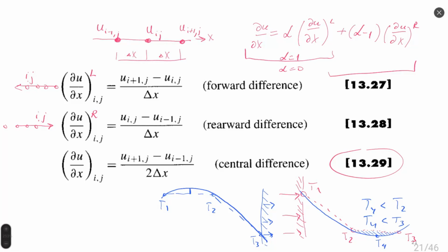Approximation by a line is called first order approximation, and you can find it in solution methods when you use ANSYS Fluent, you already remember, right? That you can choose first order approximation, second order, third order, etc. So first, second, and third correspond to the order of the polynomial which approximates your derivatives. This is why I do not always like it when people choose second order approximation, because you can overestimate or underestimate flow properties. This doesn't happen always. There is a way to compensate this error inside Fluent, but this method should be used really carefully.